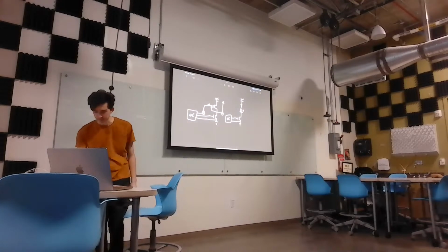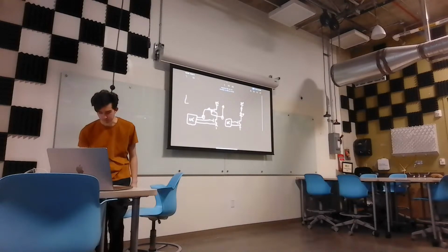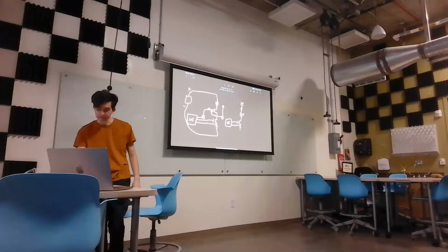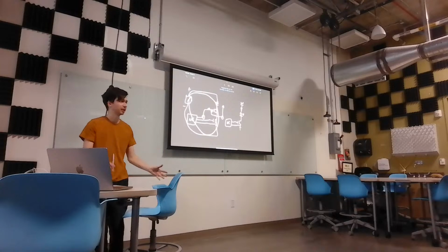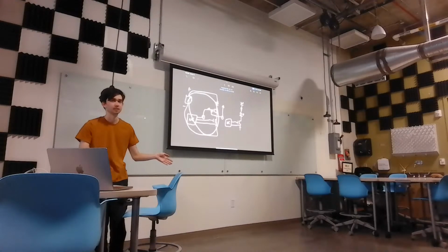So this is our battery. We got a big old battery connected like this. If this is on, it's like a wire. If this is on, it's like a wire. That's a short circuit. These FETs shall never both be on. If you understand and agree with that, great.